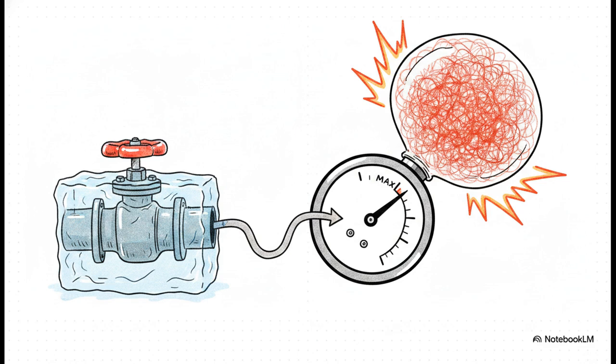It just sees the error persisting, so it blindly calculates and accumulates that error, pushing its output up to 100%. When that valve finally snaps open, that accumulated value is so massive that the system violently overshoots the target. It's a real issue, which is why engineers have to program in special anti-windup logic.